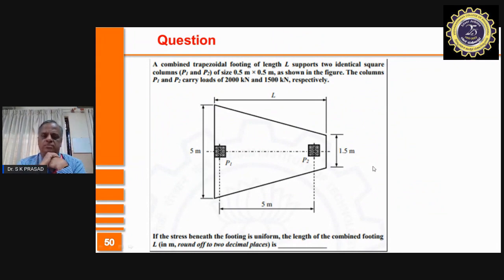Let me go further. I talked to you about the different types of foundations, shallow and deep. Shallow foundations are preferred, and in this, isolated footing is what is preferred. Why? Because it costs less. You don't require sophisticated equipment. You can do the work faster. You don't require too much expertise from the engineer or the labor force. Therefore, the isolated footing is preferred.